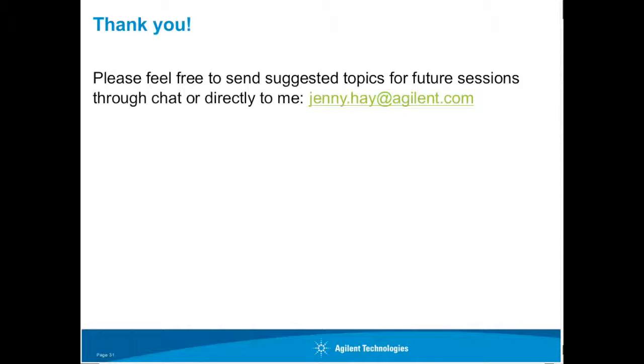Thank you, Jennifer. Our next question, first of all, thank you for the exhaustive presentation. And here's a simple question. Did you record the variations of the nano-indentation's values related to the measurement surface's orientation toward the main crystallization plans? Well, for the only force displacement curve that I showed in this presentation, the material was fused silica, which is isotropic, so there's no difference in orientation. That's why we choose it as a standard.